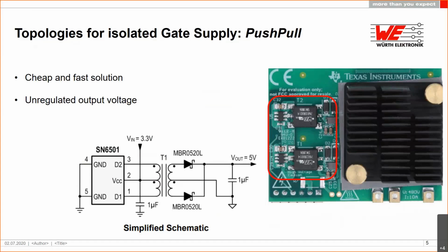So you need a very stable regulated input voltage to have a clean and stable output voltage, because there's no feedback loop in the system. And the tight input voltage range means you for sure need a pre-regulator, so there must be a DCDC or another LDO to provide the clean voltage on the input of this system.